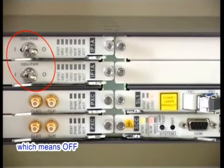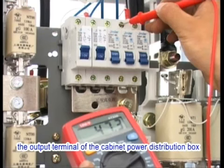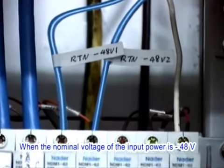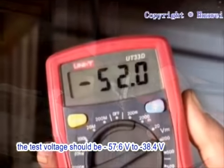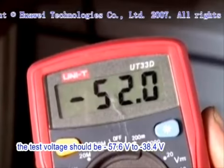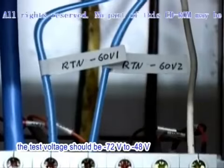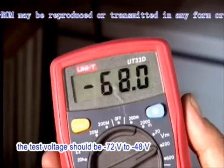Connect a multimeter at the input power supply, for example, the output terminal of the cabinet power distribution box, to test the voltage and polarity of the input power. When the nominal voltage of the input power is -48 V, the test voltage should be -57.6 to -38.4 V. When the nominal voltage of the input power is -60 V, the test voltage should be -72 to -48 V.